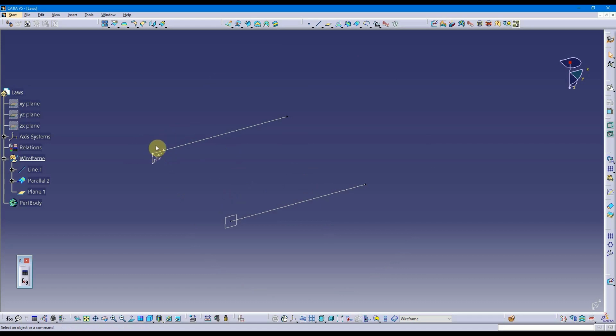So I'm going to create a sine function, and I'll just give you the parameters here for the sine function. It will have an amplitude of 10 millimeters. This line, by the way, is 100 millimeters long. So it will be 1.5 revolutions. So the sine function will be 1.5 revolutions with an amplitude of 10, and it'll be a positive sine curve.